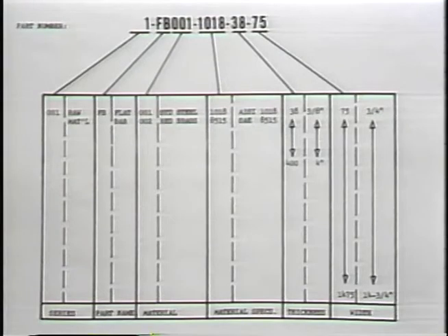Now, in this case, we got two types of material, 001 and 002. And then we get into the specific alloy definition of that material. 1018, which is AISI 1018 steel, and the other one, SAE 8515, is the red brass.